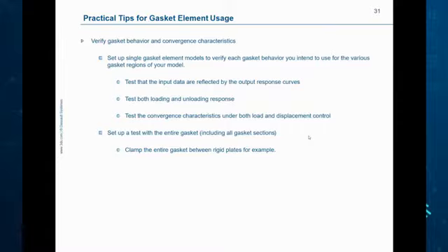This would be a good tip for any kind of novel feature that you put into an Abaqus simulation. So if you have a complicated material model, make sure it's doing what you expect it to do. If you have a complicated connector element behavior, verify it with a simplified model. If you're applying an acceleration and you think it's going to slightly deform the structure, but it starts deforming it largely, maybe you should have tested that acceleration load with a small model to make sure it looks right.